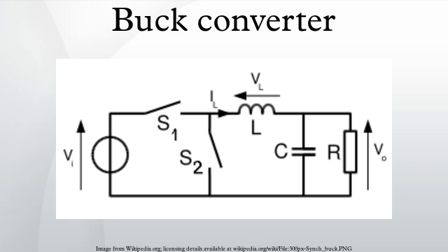On the limit between the two modes, the output voltage obeys both the expressions given respectively in the continuous and the discontinuous sections. In particular, the former is as follows. So ILM can be written as. Let's now introduce two more notations, the normalized voltage, defined by the following. It is 0 when the output voltage is 0, and 1 when it equals the input voltage. The normalized current, defined by the following.